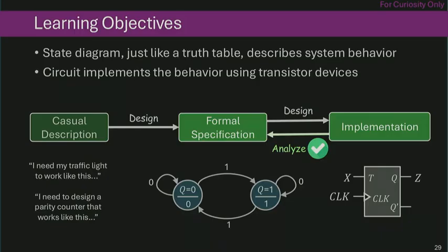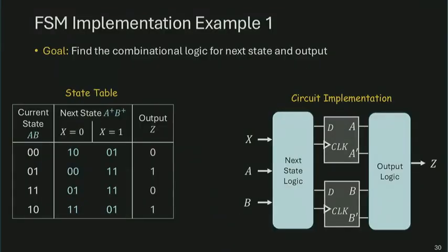Now we're going to move on to the implementation. How to convert the FSM diagram into an implementation? Well, we essentially just reverse the process. Given a state diagram, we can first put it down as a table so that we can more easily analyze the combinational logic. Eventually, this will be translated into combinational logic. By putting them in this 2-dimensional space, following the K-map shape, it's easier for us to derive the combinational function. The goal is to convert the circuit into that picture.